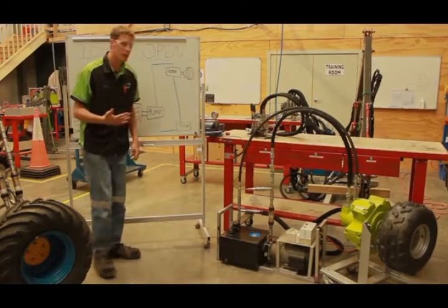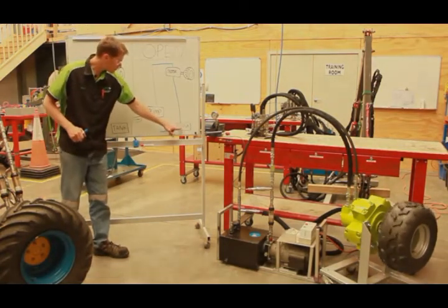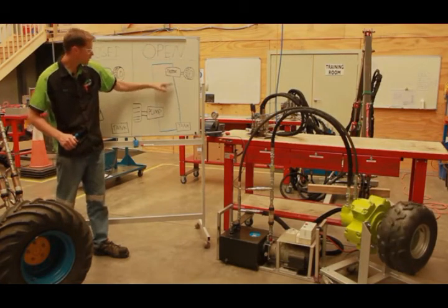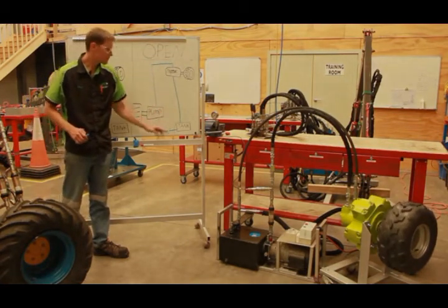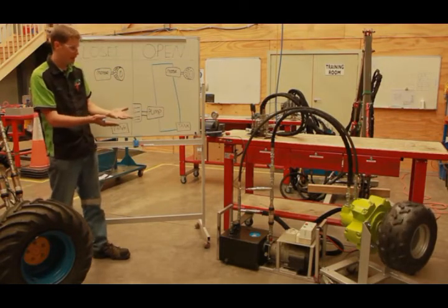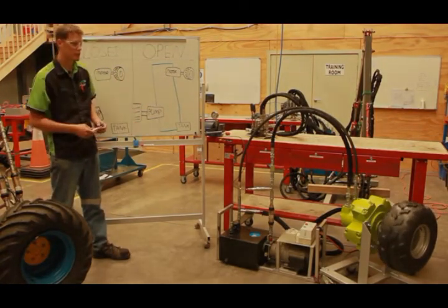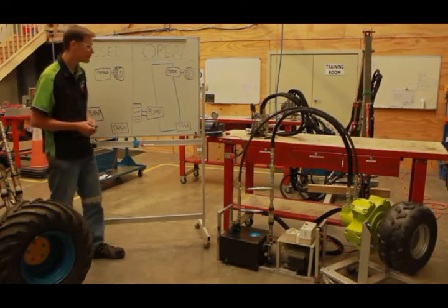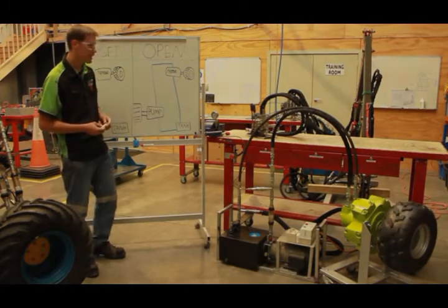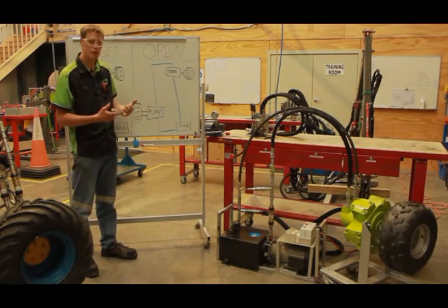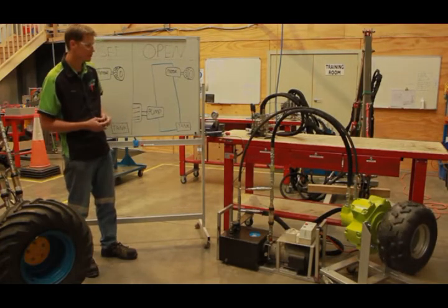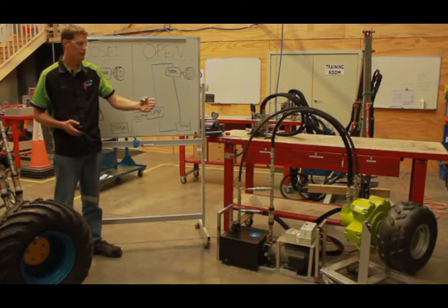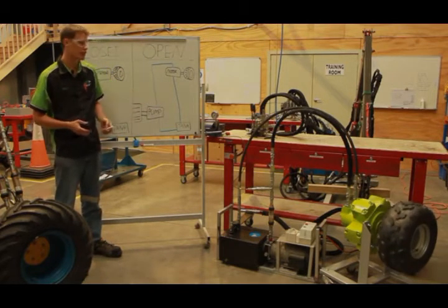So my path of oil in my loop comes from the tank, sucked into the pump, pushed out through the motor and back into the hydraulic tank. And at the moment, all the oil from the pump is going through the wheel, so I don't actually have any control over that oil. So what I have to do in an open loop system is install additional valving in order to control things. For a start, we're going to put in a directional control for if I want to turn the motor in the opposite direction.